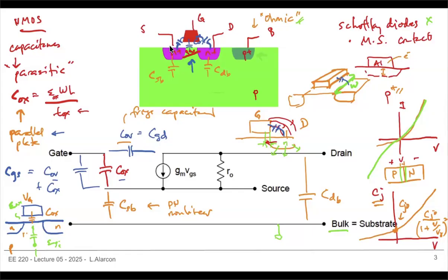And if there are two capacitors in series, you expect that if I plot VGS versus the oxide capacitance, in accumulation it is relatively high, just because it is just the oxide. But as soon as you start increasing the voltage above zero, it actually goes down because you lose that accumulation layer, and it becomes a series cap.